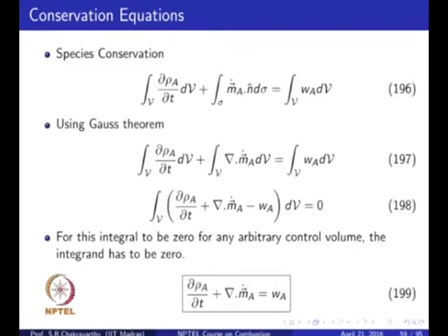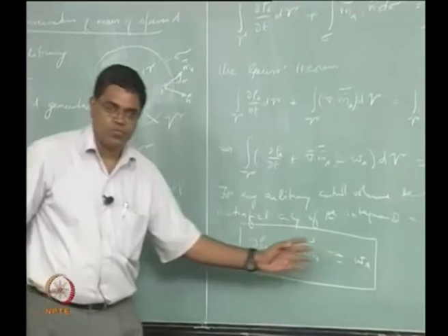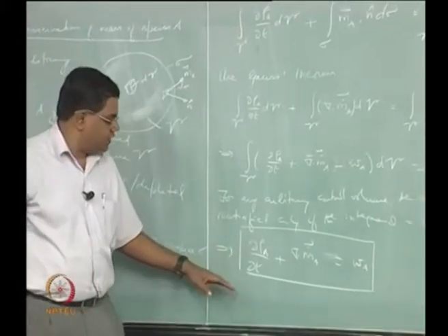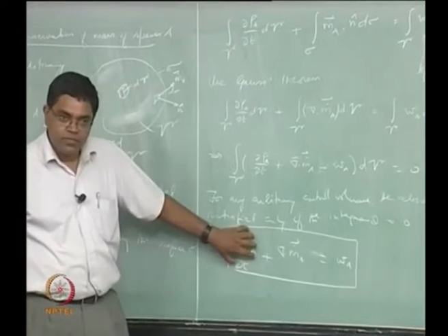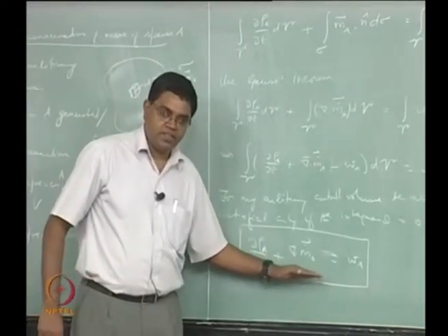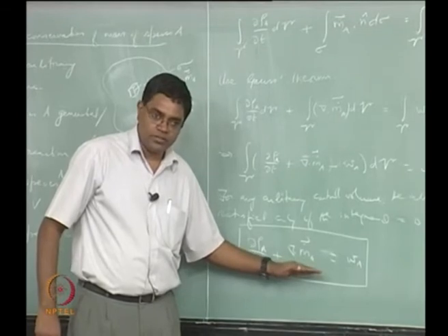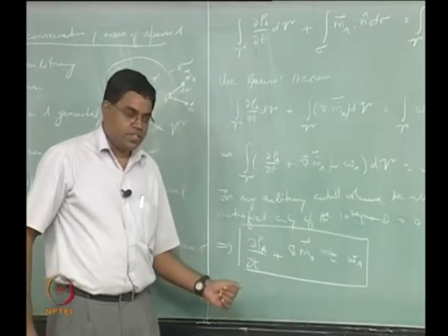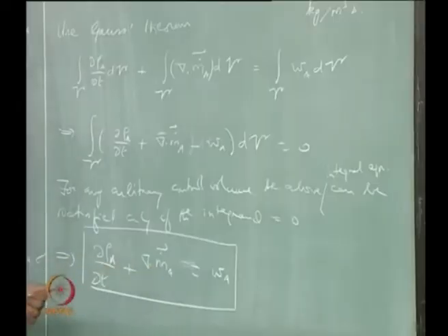Alright. We are still not quite looking at the three fundamental processes of combustion showing up here, although we see three terms. This is an unsteady term, but this actually embeds convection and diffusion together, because this corresponds to rho_A V_A vector, where V_A vector is the velocity of species A in a laboratory fixed coordinate system or a stationary frame of reference.